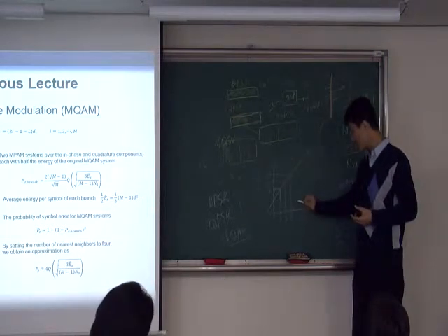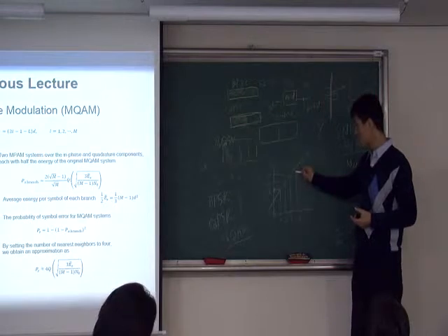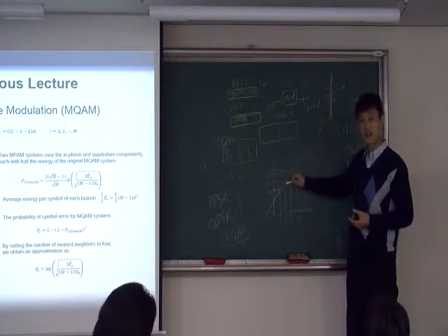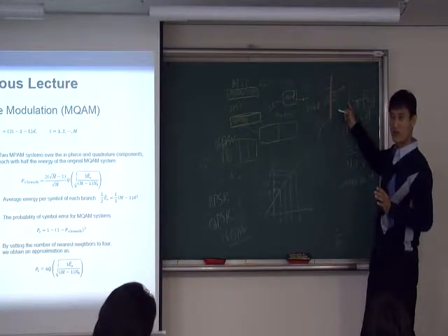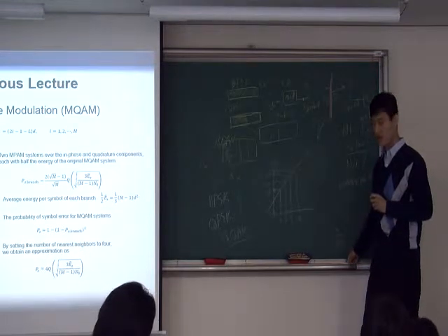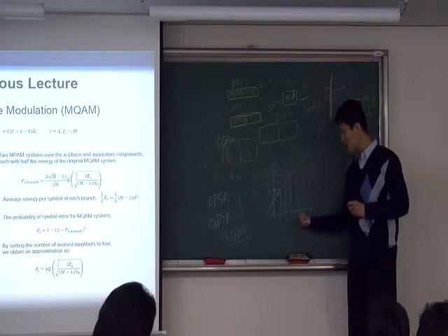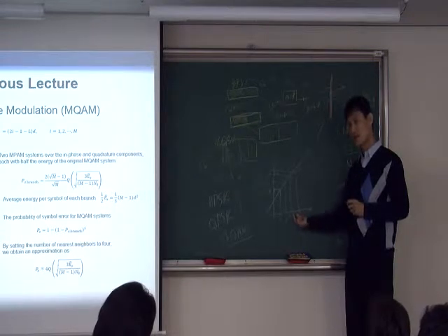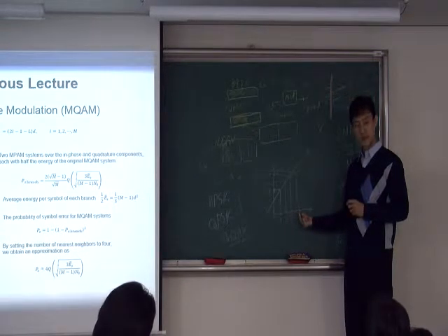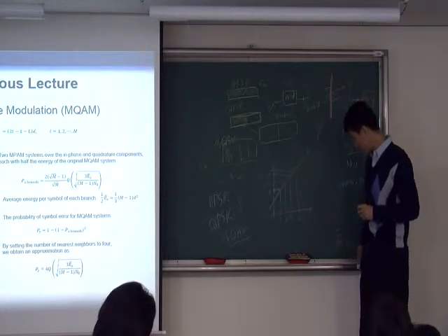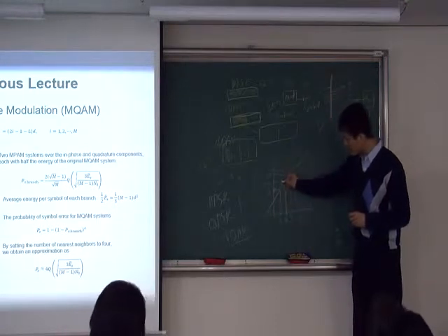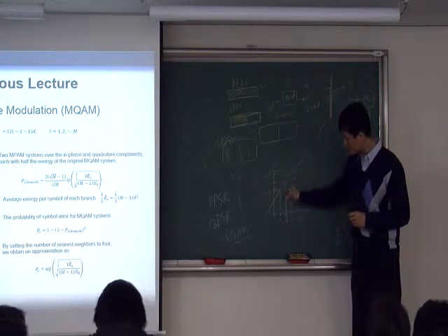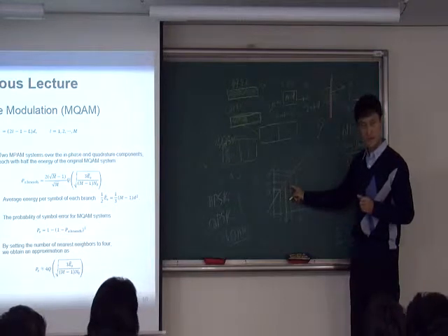So if you have some high power, it's no longer 40, it's less than 40. That makes a distortion of your signal. Such a distortion will be received very differently. Therefore, you have a very high error in that case, right? So typically, changing the energy in the baseband is not a good thing. The best way is you make sure that you have the same energy every time. That way, you make sure that the energy is inside the linear region. That's the best one.